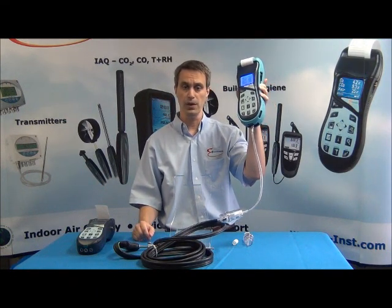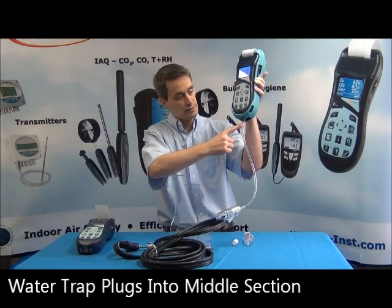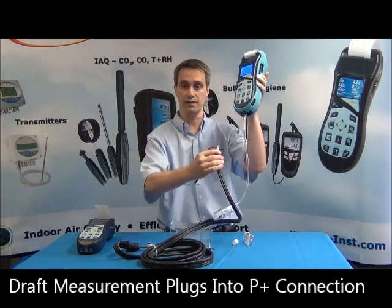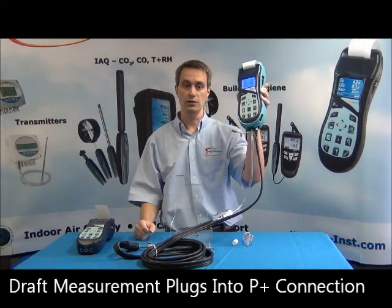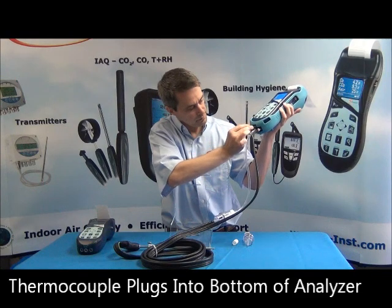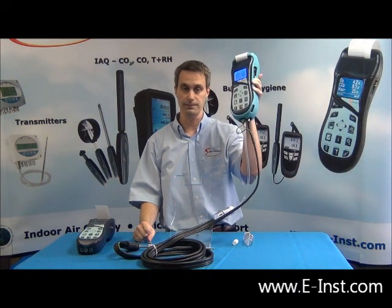Now let's connect the probe. All the connections on the unit are form-fitted to prevent you from plugging the probe incorrectly. The water trap, once again, plugs into the middle section at the bottom of your analyzer. The other connection is for your draft measurement, and that connects to the P-positive connection on the right side of the analyzer. You also need to plug in the thermocouple connector at the bottom of the instrument for your stack temperature measurements. Now you're ready to install the probe into the stack and begin the combustion analysis and emissions monitoring.